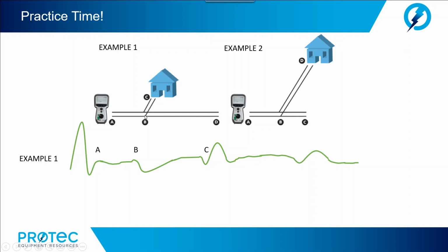Therefore, the pulse that travels down the branch reaches the impedance mismatch first and reflects back to the TDR. Meanwhile, the pulse that went through the branch and continued along the main cable finally reaches its destination or termination at point D, and again we show it represented as a high impedance termination or possibly an open circuit.